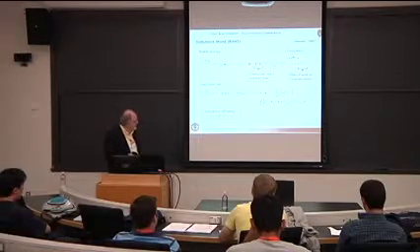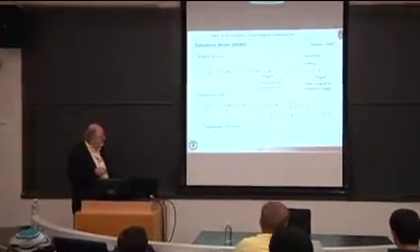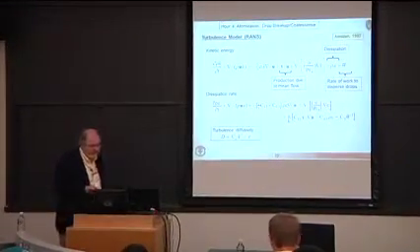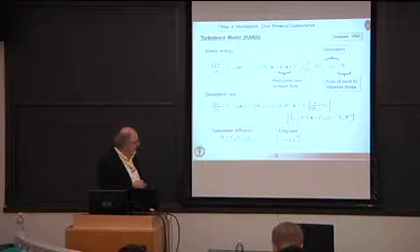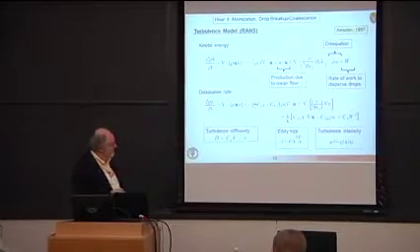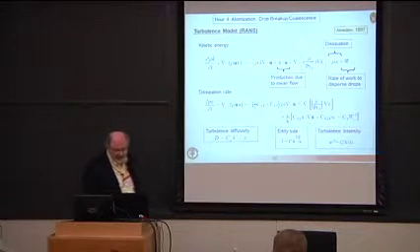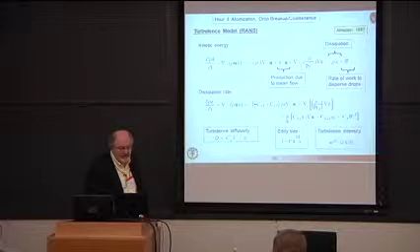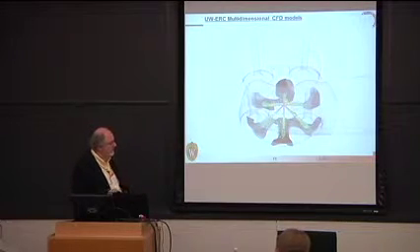The other thing that the turbulence model gives you is an estimate of the turbulent diffusivity that comes from K and epsilon. Again, we saw that yesterday. An estimate of the eddy sizes, again, comes from K and epsilon. And, of course, the turbulence intensity itself, we can relate that to the turbulence kinetic energy. So the turbulence model is kind of the connection between the interaction of the spray and the gas phase, the work done by the droplets on the gas phase.